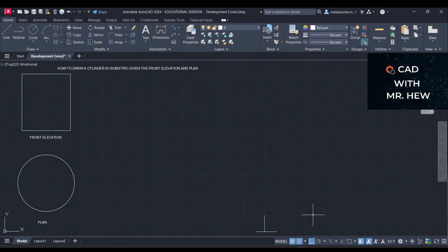That line is the starting position. The line is about 10 millimeters by 10 millimeters. With the t-square, we draw this horizontal line, and with the t-square and set square, we draw that vertical line. That indicates the starting position, the lowest point for the isometric projection.